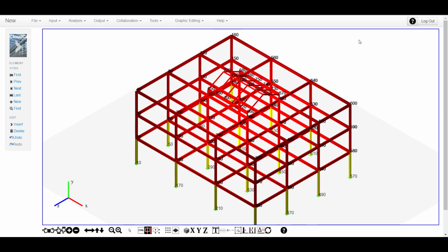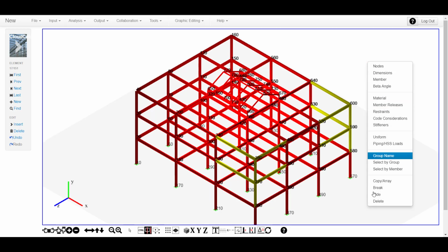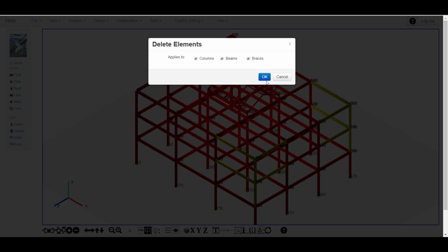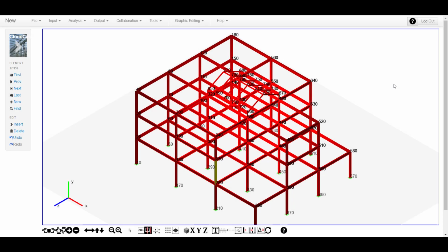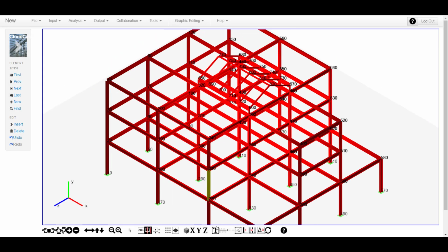Now let's say we want to make some more complex modifications. We want to modify the building by cutting back the upper stories on 2 of its corners. Select all the members you wish to remove. Be careful here, but remember, in cases where geometry is congested, you could simplify by hiding the extraneous members. However, once you have got them all selected, click Delete on the context menu, and then go ahead and admire your handiwork.